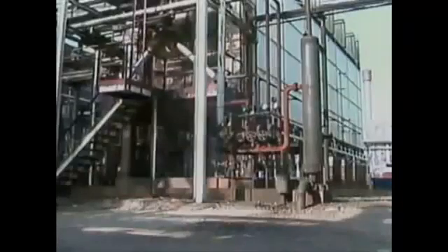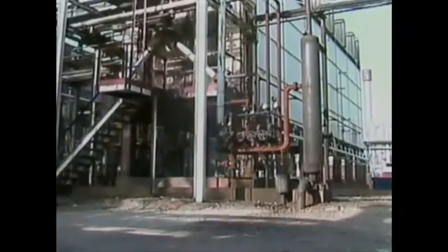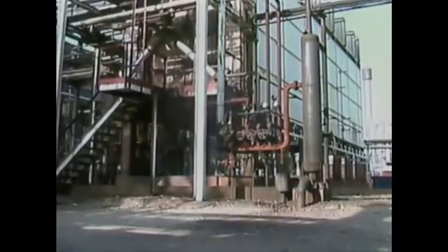The flow rate may have to be increased through that pass to equalize the flows through the furnace. Adjusting flow rates and firing rates are short-term solutions. They'll let you keep the furnace going temporarily until the problem can be fixed. But if there is a lot of coke built up in a tube, it should be removed. Many furnaces have decoking systems to remove the buildup from the tubes.